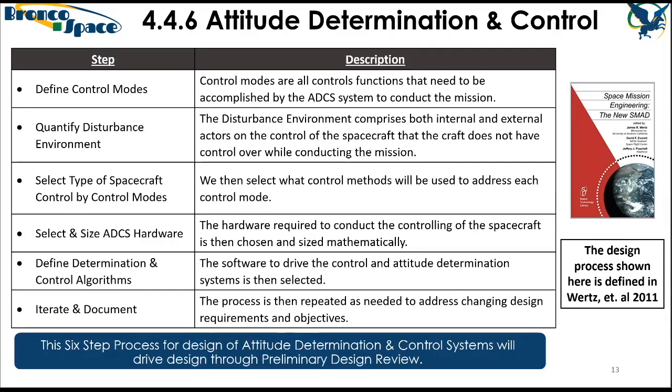Probably the one that you're going to learn very quickly, right, in the CubeSat space is a detumble algorithm for magnetorquers known as B-dot. B-dot is kind of what you think it is, where you're basically taking the dot product of the ambient magnetic field compared to the magnetic field your spacecraft is able to produce, and you use that in order to get the difference down to zero, right? Like you're basically canceling out all of the rotational energy of the spacecraft until there's no change there. Relatively simple algorithm.